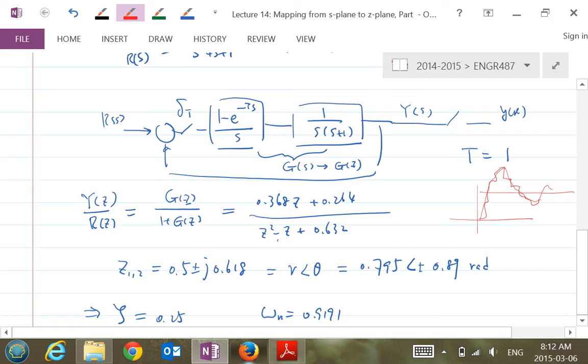Is that because of the extra integrator, like it gets bigger? Because as the sampler holds it at a lower value for a little longer, the error builds up more, or is that just...? Yes. Actually, introducing this zero-order hold, you're introducing a phase delay into the system.